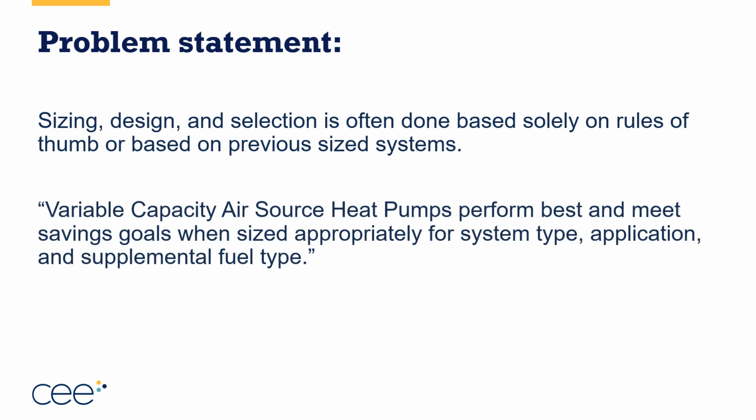And variable capacity air source heat pumps perform their best and meet the savings goals when they're sized appropriately for the system type, the application, and the supplemental fuel type. We'll get into this a lot more, but this is the goal, right? This is when they work their best, so we want to get that appropriate sizing for the system type, the application, and the supplemental fuel type.